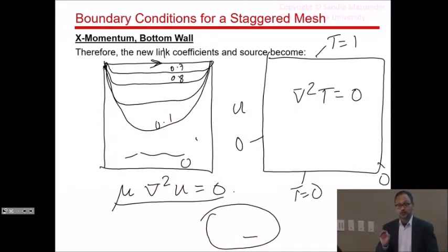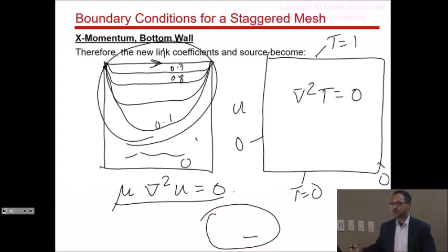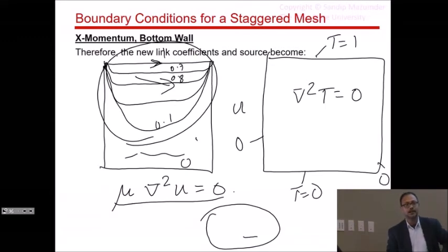If you do not use initial guess of U equal to 0, V equal to 0, then these profiles will no longer be symmetric because what will happen is now flow will push that profile this way. Okay, it will get skewed. If, for example, you used a positive U velocity. All right? Everybody get that?